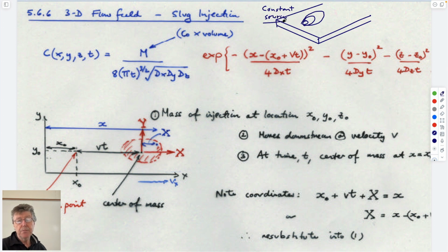so in other words, I suppose a constant source would be that you dig a hole in here, you'd put some dissolvable TCE or some nasty substance in that's at irreducible saturation, and you leave it in here so the water can wash through here and carry it downstream, but it always starts here at the same concentration. Then you'd expect a plume to look like this.